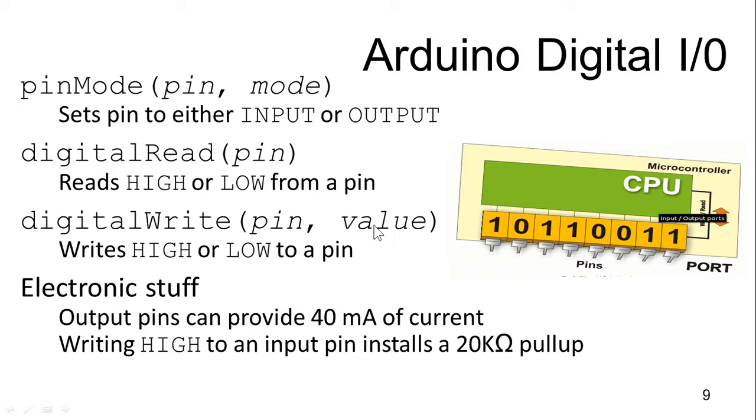If you are using a strong motor which may need higher current, you need to connect it through some interface, through some transistor or relay.